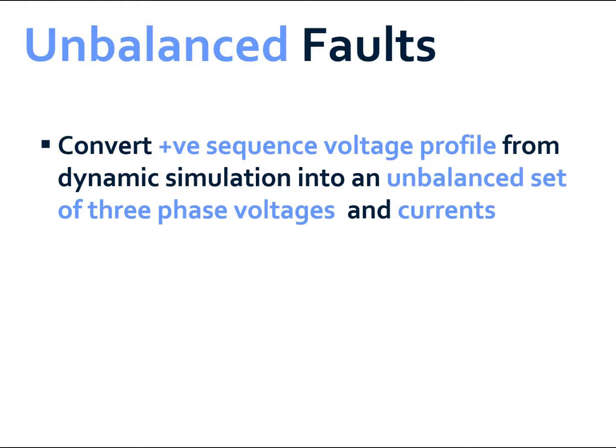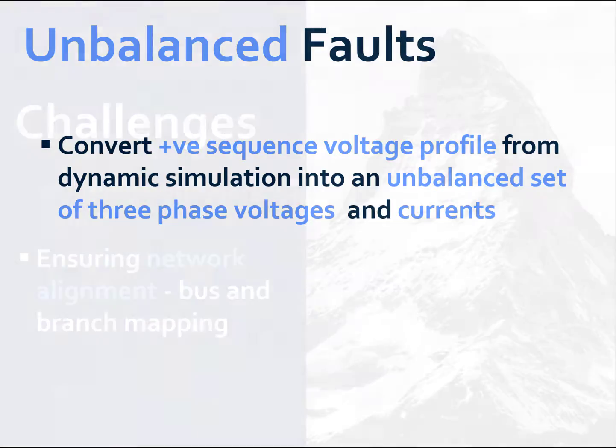For unbalanced faults, which are typically represented as balanced faults in the positive sequence network of transient stability calculations, it was necessary to recreate an unbalanced set of three-phase voltages in the protection simulation from these positive sequence voltage profiles obtained at each time step of the transient stability analysis in order to determine the actual relay response.